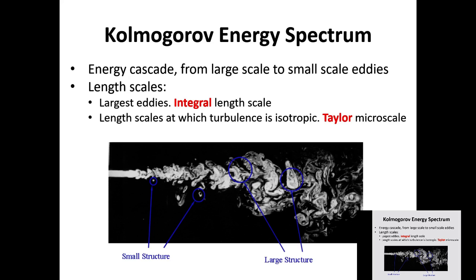But if your eddies are really small and you have a large grid, the eddy will be within the grid. Therefore, the grid won't see the eddy. For the grid to see the eddy, your grid size should be much smaller than the eddy size. Make sense?